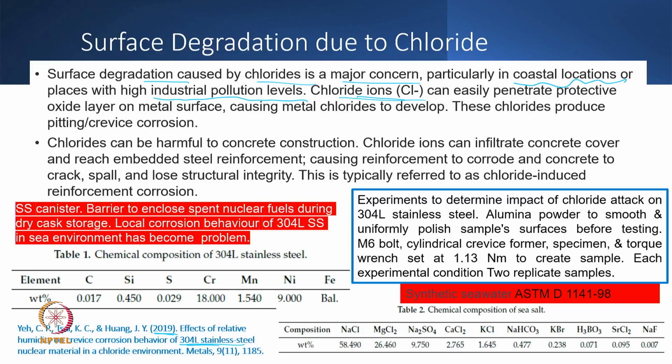So, maybe even HCl factories, or where it is formed as a byproduct. One important thing is that chloride ions have much higher chemical activity. If there is a surface on the steel, obviously there is a layer made because of the oxide, and we generally feel happy, yes, because there is an oxide layer, the steel surface will be protected, and the oxide layer will act as a protection layer on that.